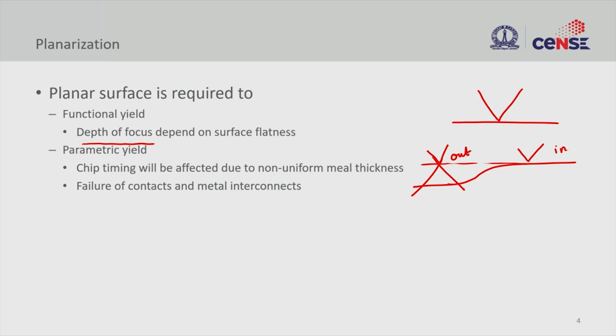So, we saw in the earlier slide the metal line thickness is varying, right, and in some cases the whole cross section can be very different, and this would result in resistance change, and this resistance change would also bring in delays, right.